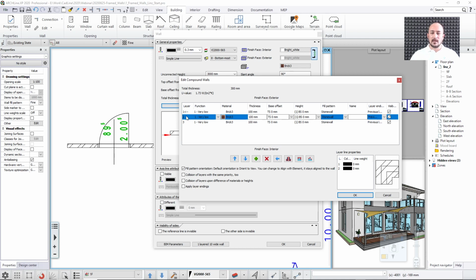I will set up the most important layer which will host the framing. So I just select it and I set up displayed layers. See that this tiny arrow has actually jumped from layer 1 to layer 2. And I will also set up the materials.